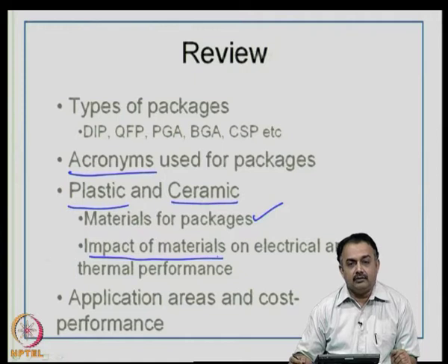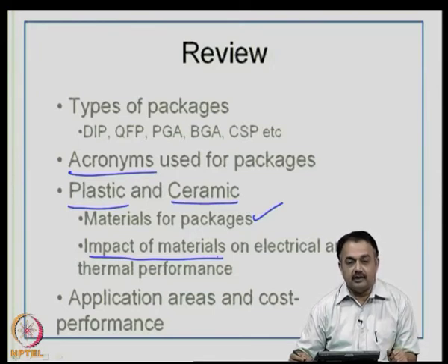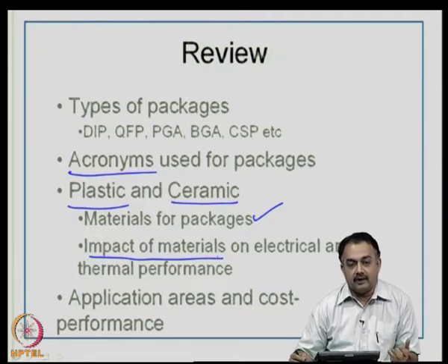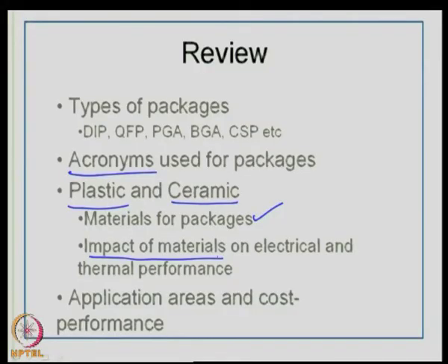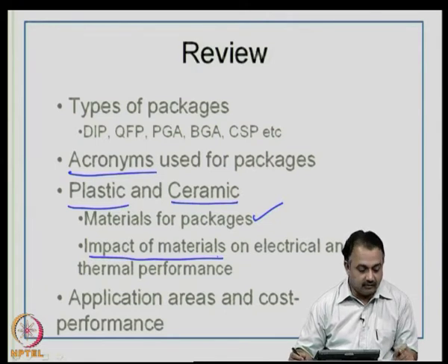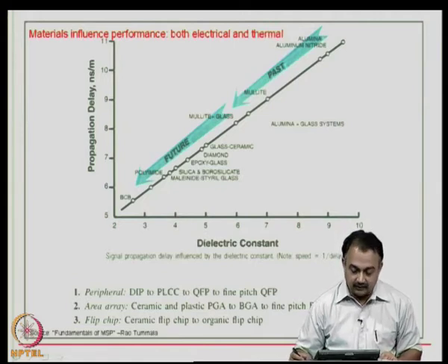Now, the packages can be used for different application areas. As I said before, you could use a plastic package for one application and a ceramic package for another application, although the functionalities in terms of electrical function could be the same. It could be a microcontroller package in a QFP format, but in consumer electronics we could probably go with a plastic, whereas for an automobile application we could go in for a ceramic package. So, application area and cost versus performance are very key drivers for the package selection and also the package manufacturing. So, we will now go ahead with the other topics in packages.